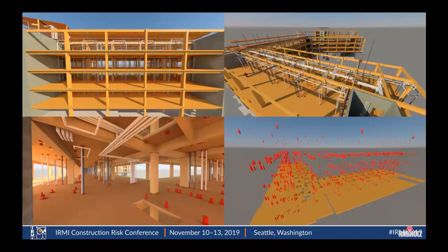The thing with mass timber is that you have to model everything in its entirety before you can fabricate it. Any hole and every hole that's greater than 3 inches has to be designed into the model before you can fabricate the CLT. It's easier for them to do that in the shop, but secondly, the engineer needs to evaluate it and make sure that you're not turning that horizontal platform that people will be walking on with live load and dead load into a Swiss cheese that would ultimately fail. So those all have to be assessed on location for function and then for structural integrity.